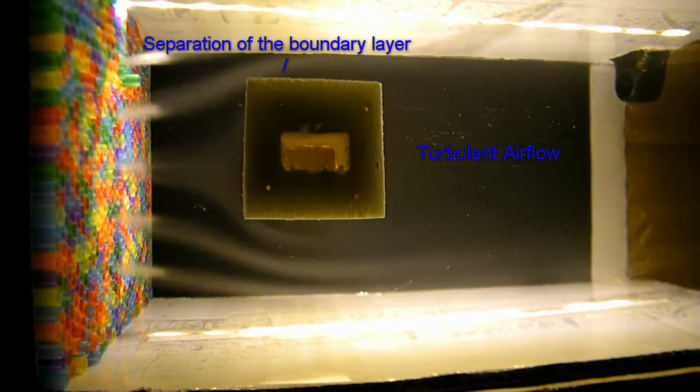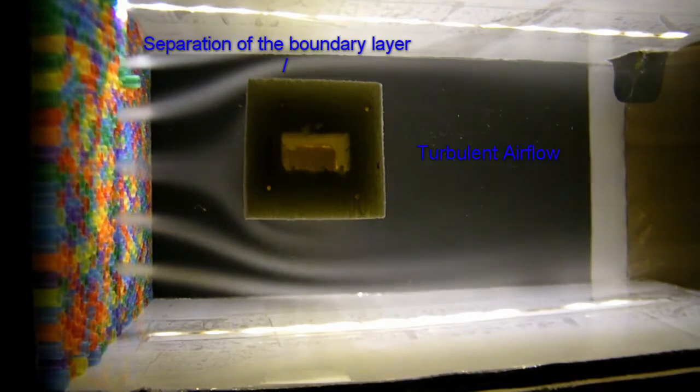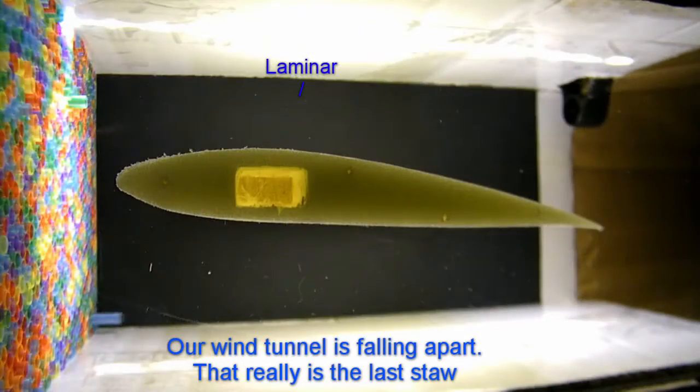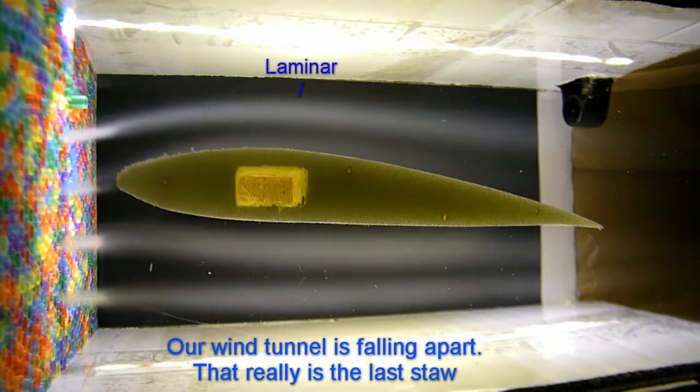We ran 3 tests in our wind tunnel using smoke to visualise the airflow around different shapes. Airflow around the square resulted in the boundary layer separating from the object, which in turn leaves turbulent eddies in its wake. The airflow around the cylinder is similar but with less turbulent flow, and the boundary layer separation occurs at a later point on the object. Finally, the wing sections show laminar flow with no separation of the boundary layer.